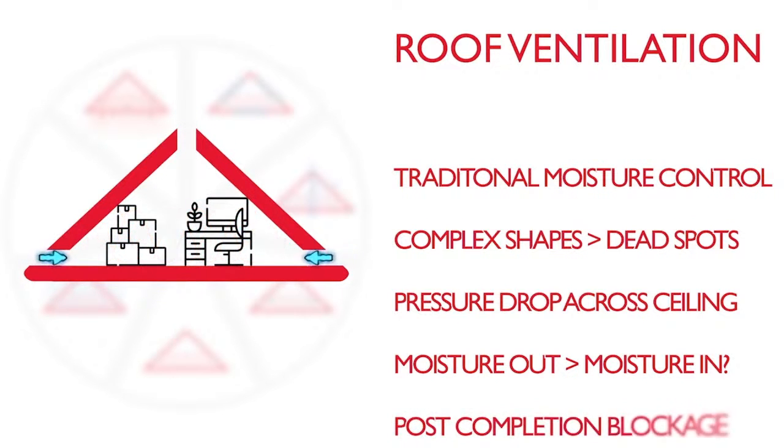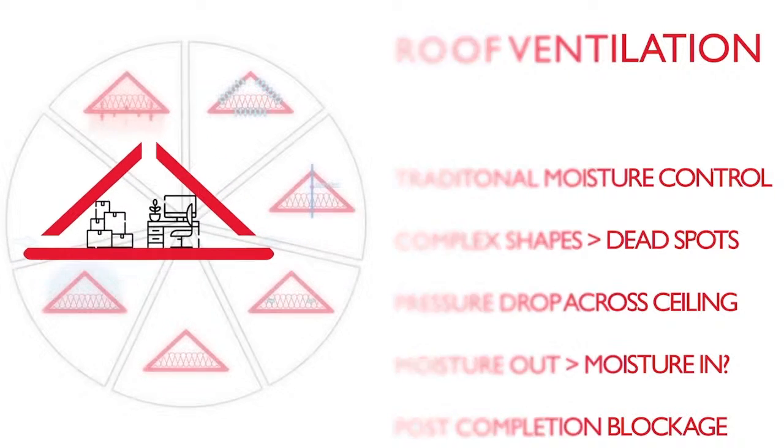Finally, any items stored in the loft may block vents, or homeowners may not fully appreciate the importance of this airflow and block up the draughts to warm up the loft. Any subsequent loft conversion may also be complicated by the need to maintain good airflow. With more people currently looking at their options to work from home than ever before, home offices are being created in lofts. Whether done properly with a building warrant or on a more ad hoc basis, it's likely to be increasingly common, making a robust and fail-safe hygrothermal envelope design more important than ever.